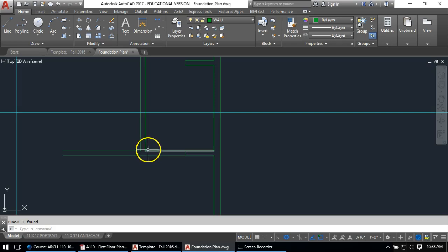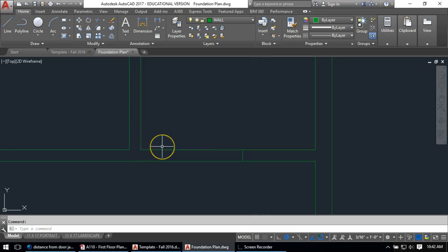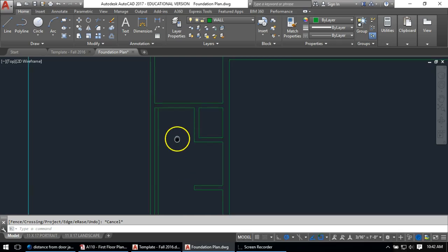So there's a little bit of wall that comes out to the right hand side here. Yeah, I don't see a dimension here. We know if you're going to get a couple 2x4s in there, you're talking about 3 inches right there plus some finish. So 3.5 inches would probably be the minimum over. I might go with that. Offset 3.5 inches here to extend that down. And now I can just trim this opening right like that. And I think that's the same